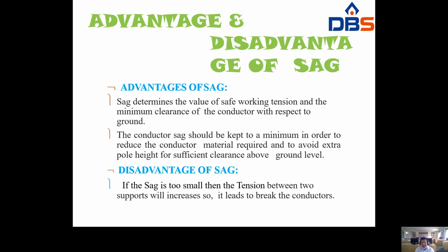Suppose what is the disadvantage? If the sag is very small, the tension between two supporters will increase. As tension increases, it leads to breakdown of the conductors.